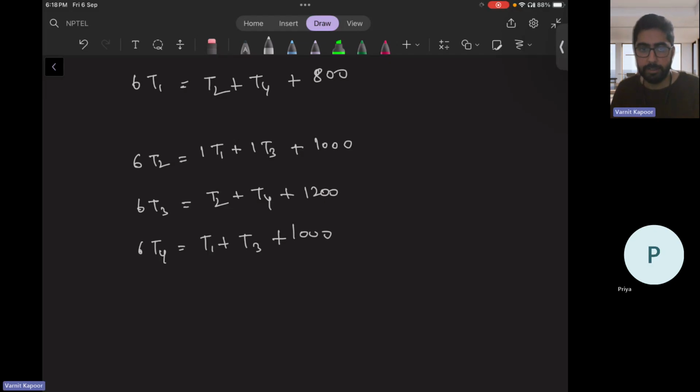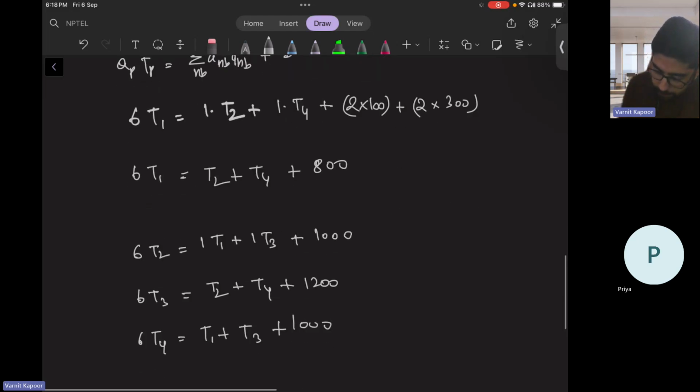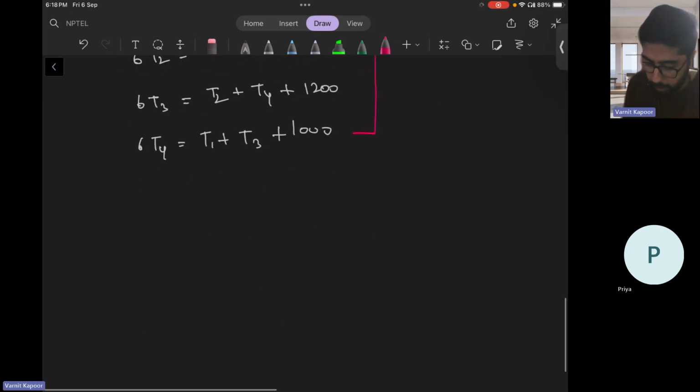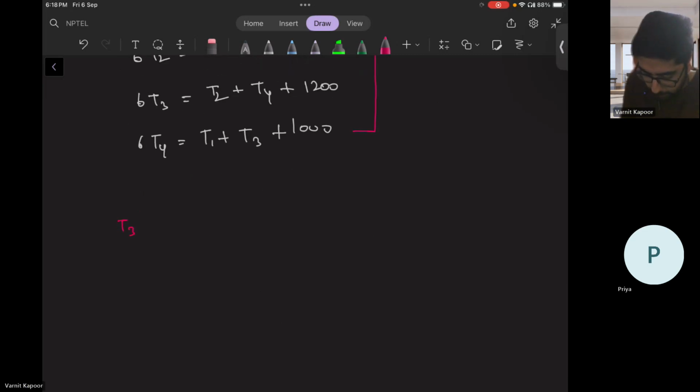Now you have discretized your domain and got the algebraic equations. Now you will solve the equations using TDMA. As you know, all these 4 equations. Now you have assumed the value of T3 star is equal to T4 star is equal to 100 degrees Celsius.